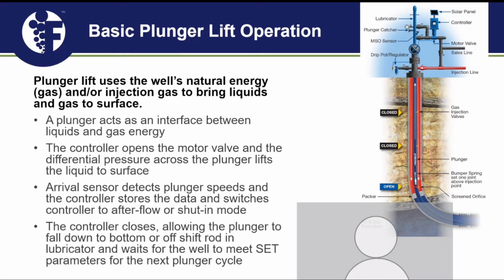Absolutely. It used to be just an old kitchen dial timer that would switch from one cycle to the next. Nowadays, most of them are some form of PLC with their own algorithms and maybe some machine learning that adjusts automatically based off of the feedback from the well. That's what we'll spend a lot of time on, the cycles. And that controller, no matter what style it is, is going to affect or control those cycles, right?